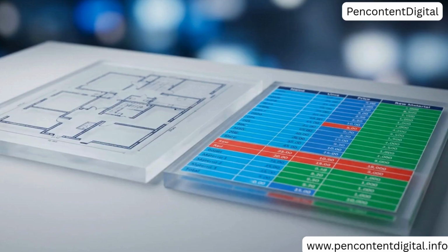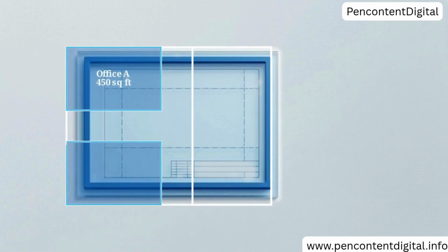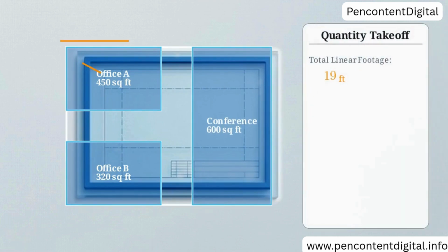That calibration enables quantity takeoffs. This is the exact extraction of material quantities, lengths, and areas directly from the drawn plans. To calculate square footage, digital polygons are traced over specific architectural zones. Because the document is calibrated, the enclosed areas instantly generate dynamic numerical readouts.